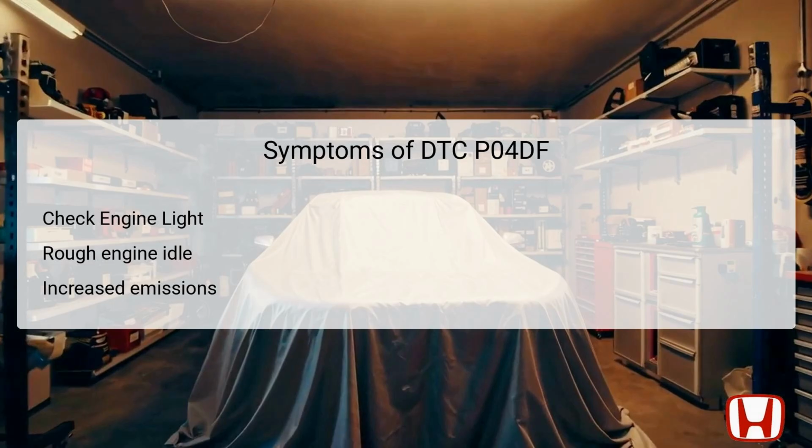The presence of DTC P04DF can manifest various symptoms that may be noticeable during vehicle operation. A primary symptom is the illumination of the check engine light on the dashboard, signifying an underlying issue requiring attention. Additionally, drivers may experience a rough engine idle, particularly when the vehicle is at a stop, due to an imbalance in the air-fuel mixture stemming from excessive vapor flow.